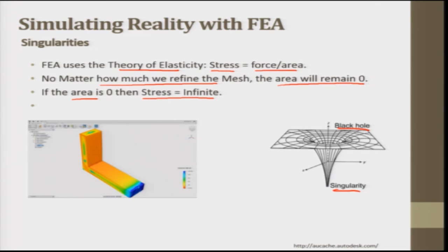Then numerical errors for the solutions of the equations, those we are putting here. So these errors can be many. This singularity is also one of the issues, I would say. A finite element model will sometimes contain this kind of singularity when the stress is very high or infinite at a specific point. So this is singularity.